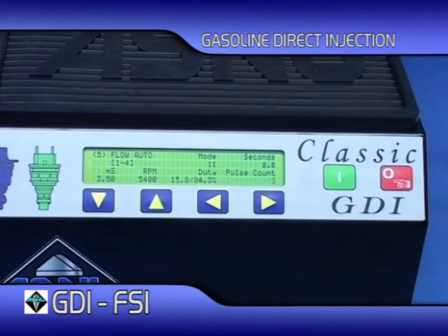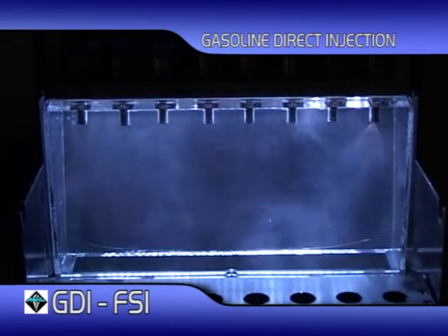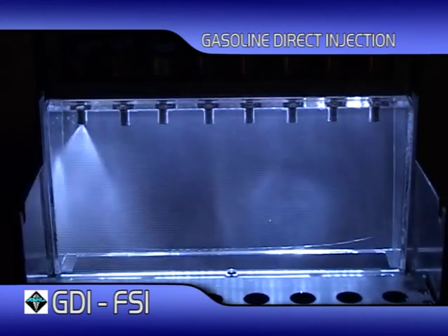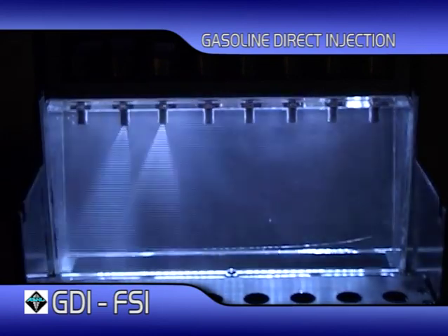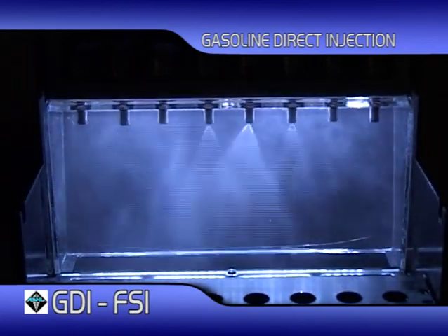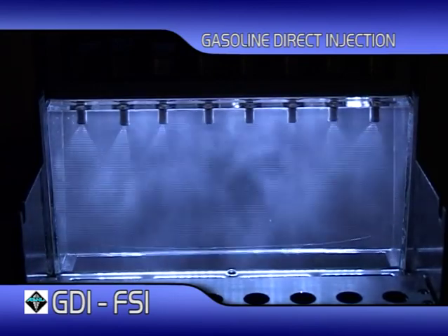If a fault is seen, the operator can return to function 4 flow mode and select the desired setting and view in more detail. This clip shows the Flow Auto mode in operation. It will run through all the modes possible for the 8 injectors. Fewer injectors will allow more test modes. The difference in the spray patterns and failure in the electronic operation would mean many of these are not acceptable to be returned to the engine. Even if the flow rates were correct, unless the sprays and operation are correct, they cannot be used.